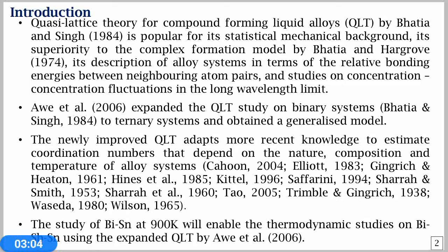The use of QLT in previous studies on physical systems has been applied with coordination number set as 10. The use of 10 as coordination number in all systems at all temperatures and alloy compositions may be a good approximation. However, improvements can be made by applying more recent knowledge, such as the knowledge of crystalline materials, which tells us that coordination number depends on the nature of materials,